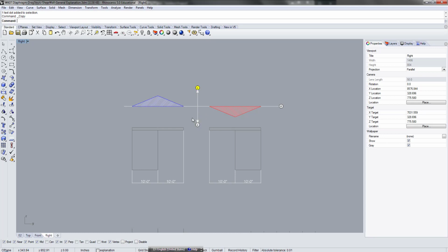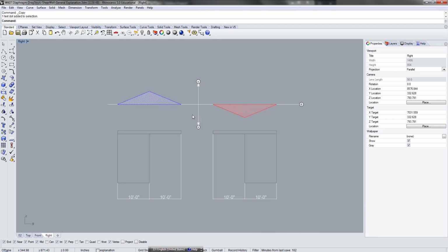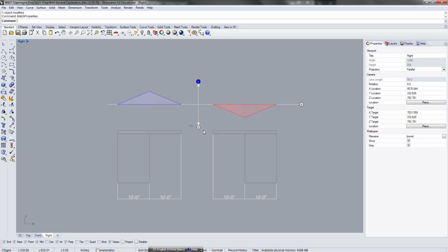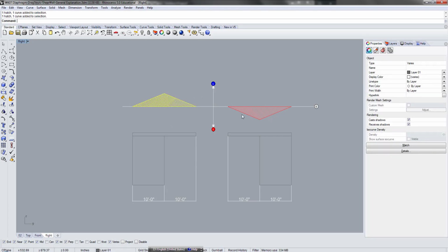I'm assuming if the value is positive, it's compression. If the value is negative, it's tension. I mean, it can be vice versa, but however arbitrary it is, you have to make that assumption to start the analysis, right? Because compression and tension are opposite. So it really doesn't matter what's above or below, but I'm just saying that above is compression, below is tension. And the assumption here was somewhat arbitrary, so I might end up getting a slightly different diagram.